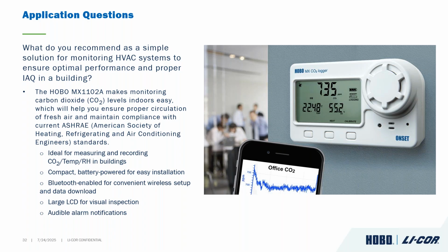This was a frequent application during COVID, as many HVAC systems had to be ensured that they were performing how they should be, as concerns of getting sick in the area were common. So you'll always have to remember that the MX1102A should be deployed right around mouth level to maximize the usage. Some of the other benefits of the MX1102A include that it's compact and battery powered for easy installation or easy moving around if you need to test in different locations.